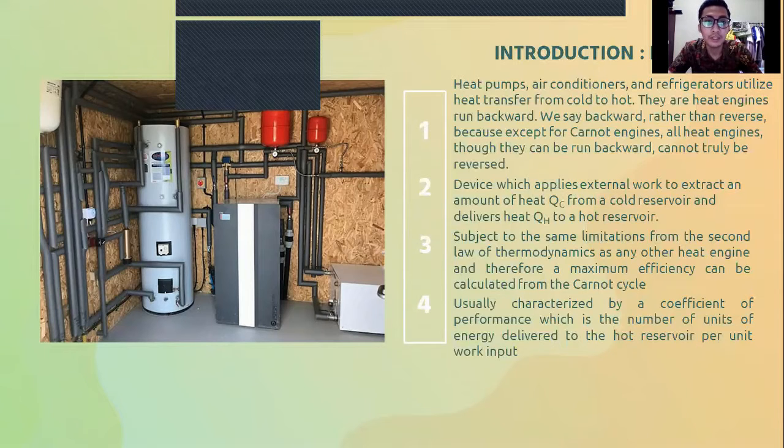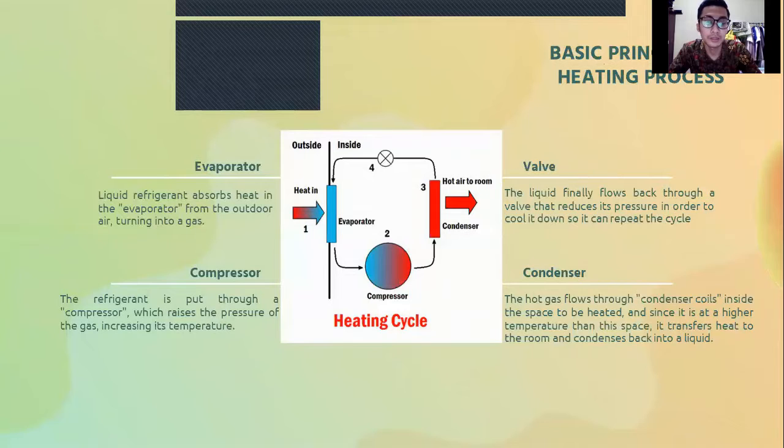Then I will talk about the basic principle. First, the heating process. In the heating process, the liquid refrigerant absorbs heat in the evaporator from the outdoor air and turns into a gas. Then it goes through the compressor, which raises the pressure of the gas and increases its temperature.